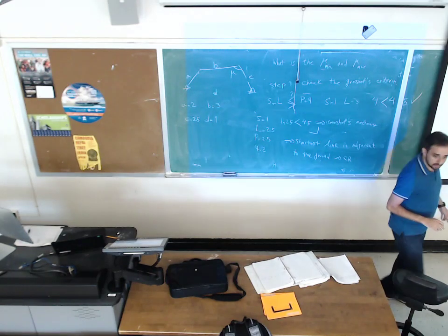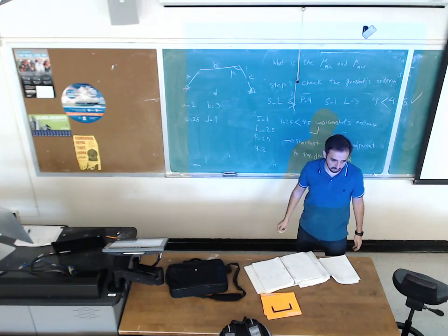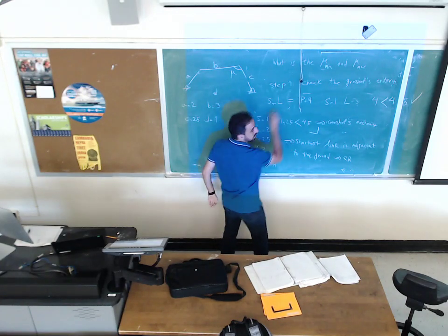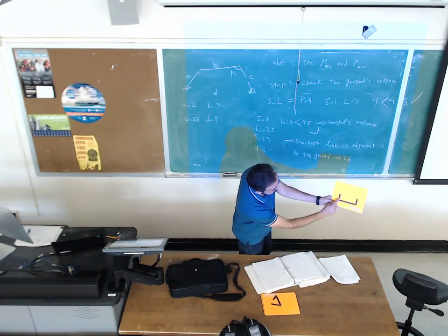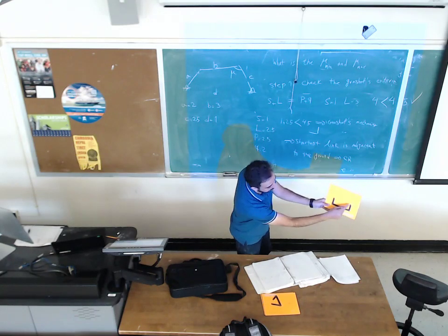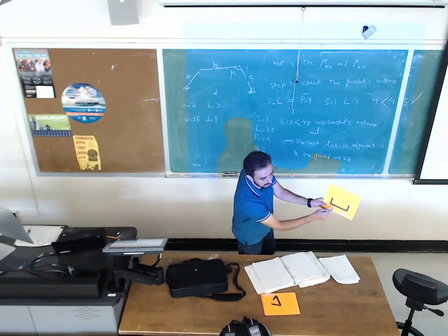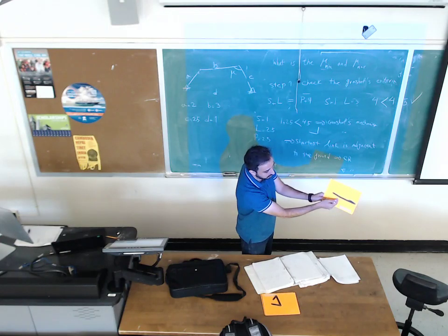Yes. I have a question. What happens when you have one crank and one rocker or a double crank, but it suffers from the change point effect, if these two are opposed to each other? If they are like this, see, this is the shortest link, this is the longest link. As you see, in this case, this one equals this one equals this. So the summation of these two is going to be the same as this. When it's moving, when it's going to pass this position, you don't know whether the entire mechanism goes up or one of them goes down.